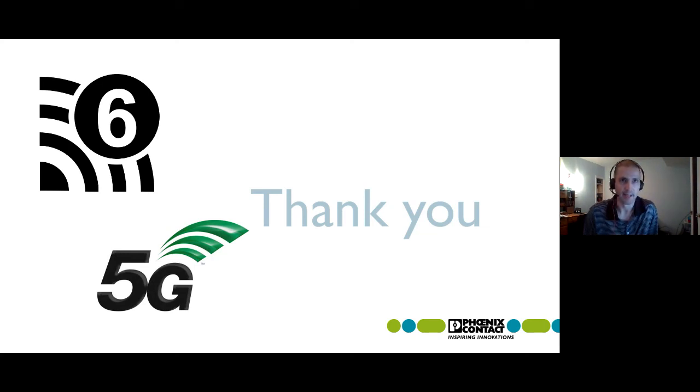My feeling is that 6 gigahertz spectrum, the Wi-Fi 6E, is really going to be more in the factory floor, indoor stadium application space at low powers, because what you're trying to accomplish with that new spectrum is capacity, right? The problem with Wi-Fi today is there aren't enough channels for low latency or reliable communication. So opening up those 6 gigahertz channels, albeit there's things using it today that are very time sensitive and need, what's the word? Critical, mission critical.